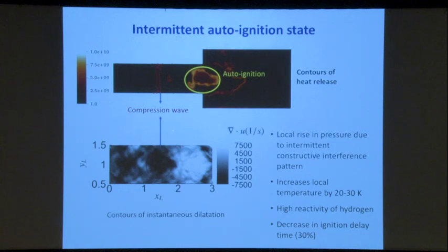And that's enough that when we had designed that mixing tube length to correspond with the homogeneous ignition delay, that's not enough to factor in these increases in temperature. And so we do see ignition occurring at shorter times and upstream of the combustion chamber. So it's a result of the pressure work that's generated from the autoignition that's happening in the combustion chamber that interacts with the walls and the sound waves to coalesce and form these sporadic temperature increases, giving rise to autoignition.